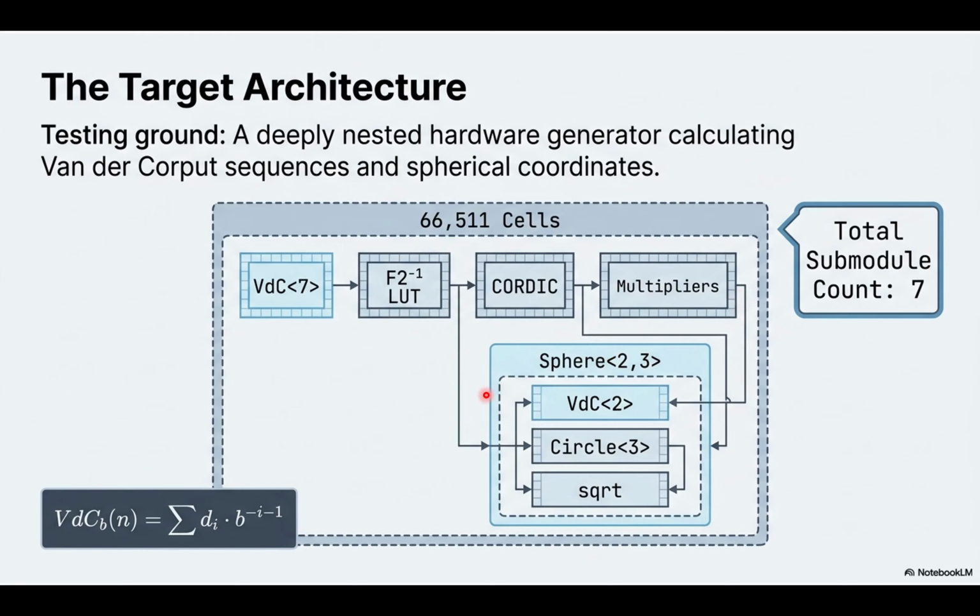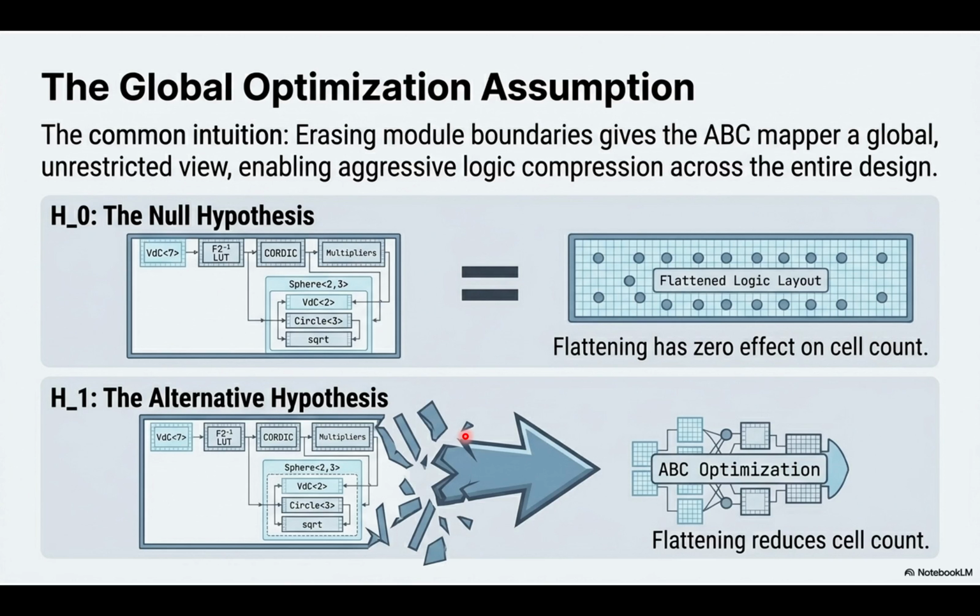Very intertwined. And to translate this pure math into actual physical silicon logic gates, the researcher relies on a tool chain called the Yosys synthesis flow. Right. That's our builder in this scenario. The setup for the study requires comparing two distinct flows, to ensure a perfect apples-to-apples comparison. Both flows start with the same initial core synthesis step. But the divergence happens right before handing the design over to the logic mapping tool, a program called ABC. And that has the critical job of actually assigning the physical logic gates. Precisely. That's its whole purpose.